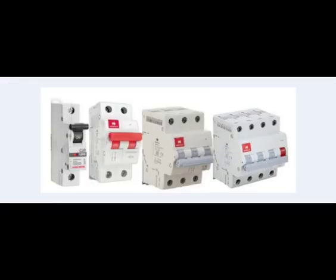Here you can see a 3-pole MCB and a 4-pole MCB. A 3-pole MCB has a 3-phase connection and does not have protection for neutral. In a 4-pole MCB you have the protection for neutral, with 3-phase and neutral connection on the MCB. Here a 2-pole MCB has phase and neutral connection, and a single pole MCB has only a connection for phase. For the neutral wire you do not have any protection in a single pole MCB.